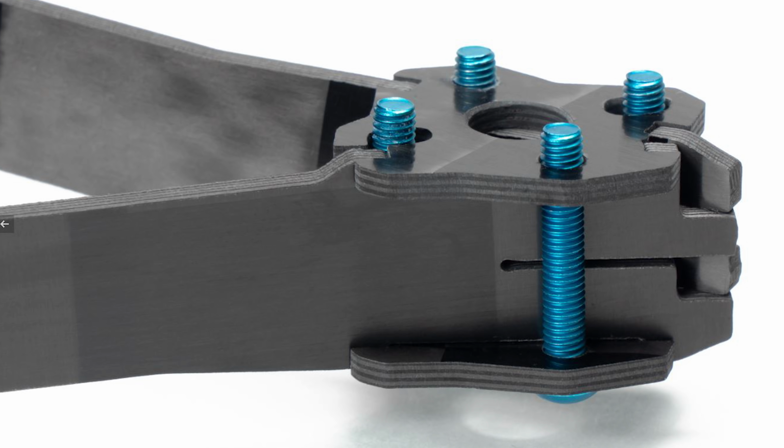The major thing is that the arms are attached to the main body in two different levels. And that means that the arms can actually cross each other without needing to have a slit in them that makes them weak. And that makes the main body way stiffer. So the main body is strengthening the arms, and the arms are strengthening the main body.